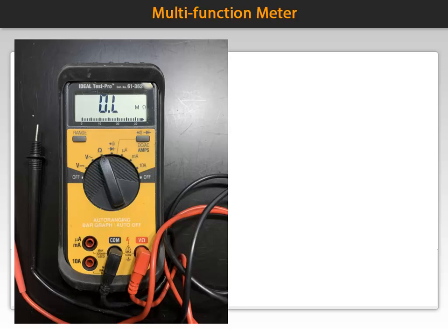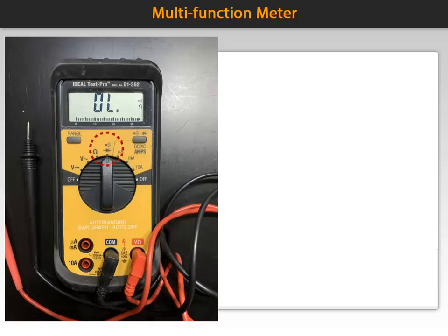No doubt at some point you will need to check for continuity. In this next position, you will find a symbol for continuity. Also, right above it, you see the audio symbol. This is helpful by giving an audible beep to indicate total continuity. This can be toggled on and off by tapping the button seen here.